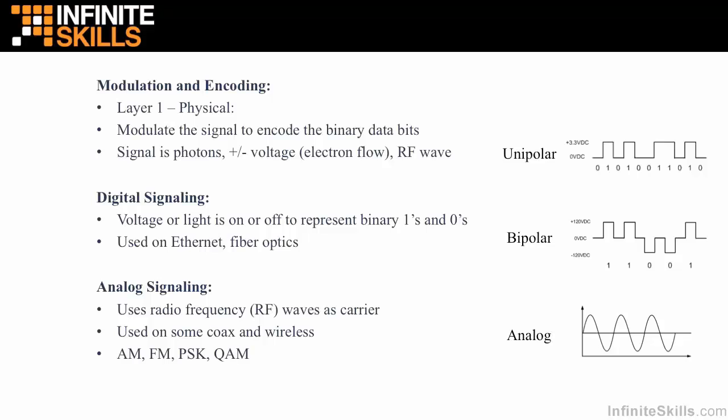That's amplitude modulation. Frequency modulation says use a higher frequency, which would be a shorter wave, to represent a binary 1, and use a lower frequency, a longer wave, to represent a binary 0. So here's another way I can modulate the frequency to encode binary 1s and 0s. Higher frequency, shorter wave equals a 1. Lower frequency, longer wave equals a 0.